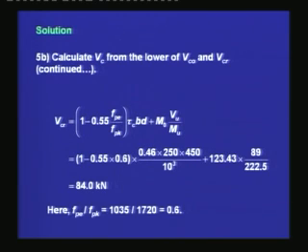Thus, substituting these values of tau c, M0, Vu, Mu, we can calculate Vcr is equal to 84 kilonewtons. Thus, this is the amount of shear that will generate a flexure shear crack.